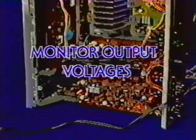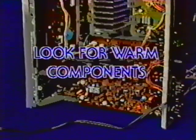If the power supply is on the same circuit board as the load circuits, observation of the individual supply outputs with a voltmeter may help identify the defective load circuit. Warm components may also indicate which area of the board is causing the problem.